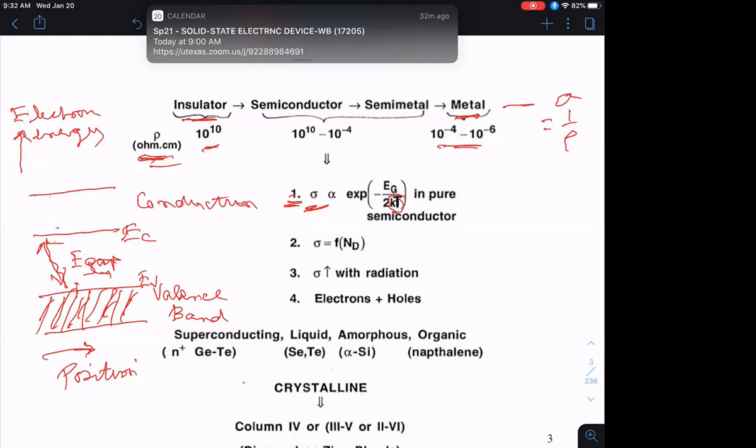On the other hand, if I now raise the temperature T, what's going to happen is the electrons in this valence band start jiggling around. They have more and more of a thermal motion. And if the temperature is high enough, a few of these electrons will get thermally excited from the valence band into the conduction band and create a few negative electrons and leave behind a few empty states, which are called holes, which you'll see behave like positively charged carriers.